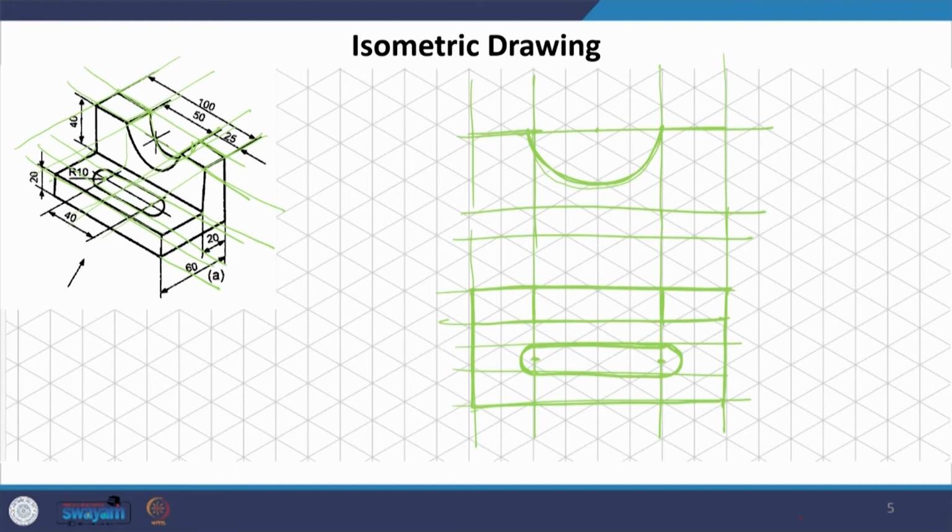In the front elevation for this one, we know that there are 2 of these which are going hollow. So, we mark these, and this is where your dotted line is going to come. This is the hollow, and the rest of it remains solid. So, drawing it as the final object, this is what our front elevation is going to be.